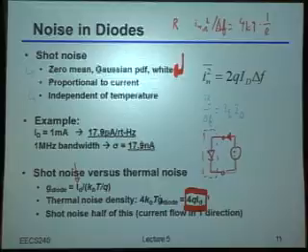But if you think about random processes and random events, if I have a barrier that's forcing current to only flow in one way, it's like saying I'm throwing away half of the random events that could have happened. Because anything associated with things flowing in the other direction isn't allowed by the barrier. So from a variance standpoint, if half of my events don't really contribute any noise, then it's as if my net variance should be half of what it would have been if I allowed both of those things to happen. Does this make sense to people?